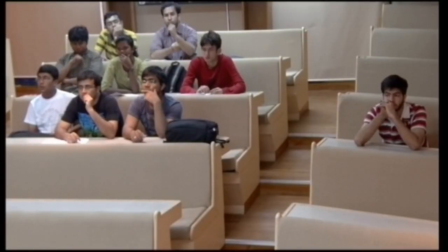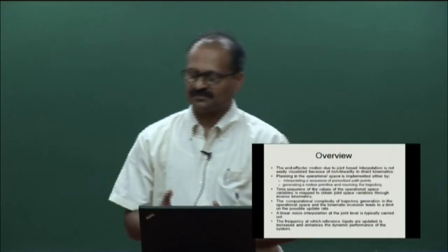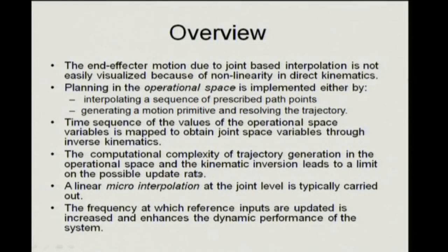Now, because you are doing inverse kinematics, and it is not only inverse kinematics, you also have to pump the data out. Typically you will have a computer sitting somewhere, and from the computer you will do the inverse kinematics, and then you will pass it out to a microcontroller to implement the local motor control loop. So there is also the data rate which you can support. Everything combined, there is a limit to how often you can chop up the data in the operational space. So we need to keep this in mind, that you cannot completely do the interpolation in the operation space.